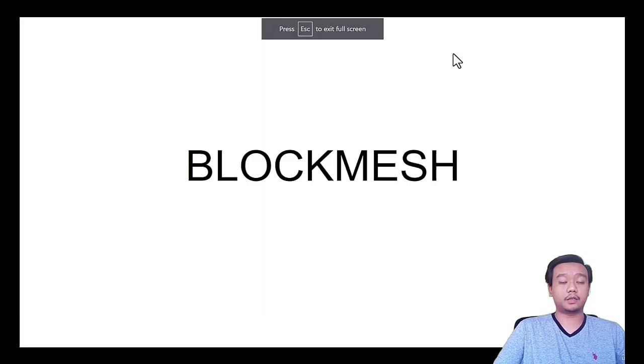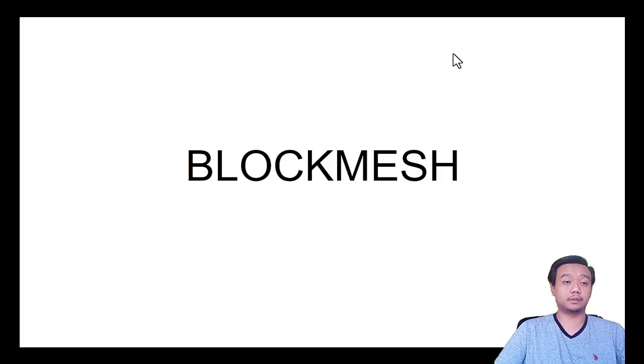Okay, in this part of this video, I would like to discuss further about the BlockMesh that we have previously used to construct our lid-driven cavity case. But in this part, I would like to explain the detail about how to set up the coordinates and how to read the boundaries.